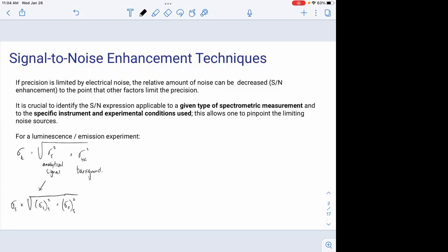If you go back to our previous video for this week, shot noise is that ejection of an electron across space when it's not supposed to be happening. And flicker noise is that thing that we can't really characterize so well, but we know it has an inverse dependence on frequency. So there are two variations of where noise could be coming from within your analytical signal.